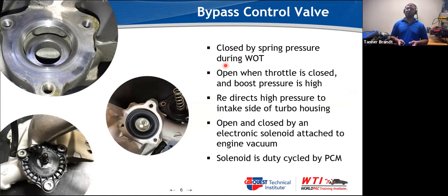Basically what we're doing here is boost pressure is built up really high, and then somebody lets off the accelerator. When that happens, we don't want boost pressure slamming into the back of the throttle plate. If that happens, you get what's called turbo surge, and you'll get a really weird whooshing sound. It's not great for the turbo. It's obviously not great for the intake either, because you could have, let's say, 15 to 30 PSI pressing against that throttle plate.